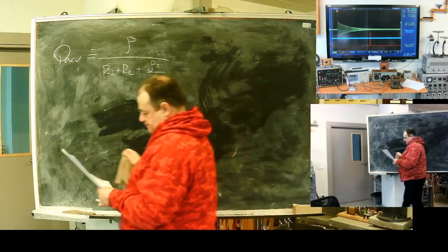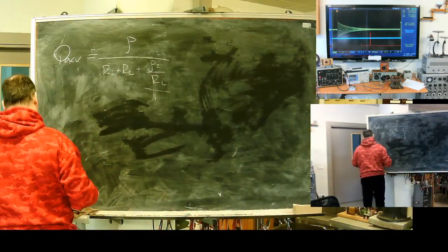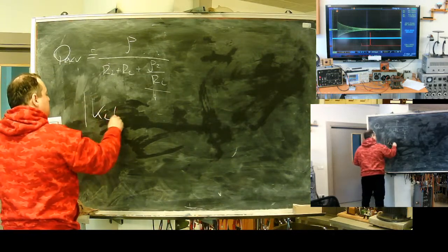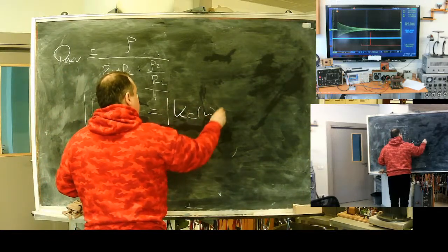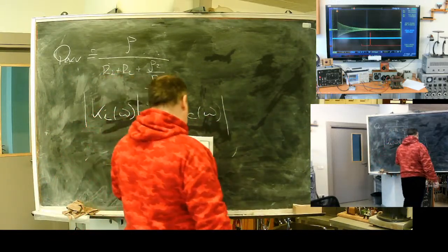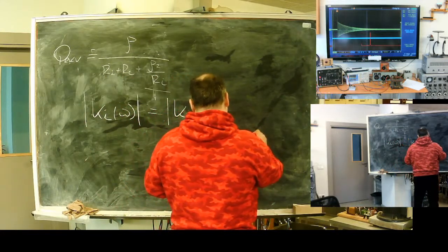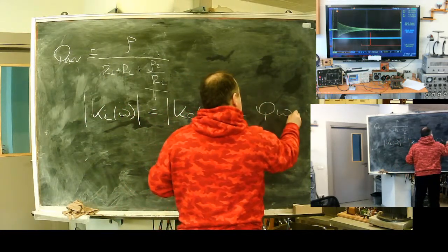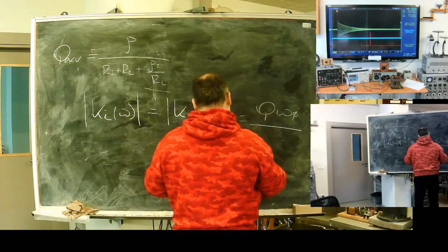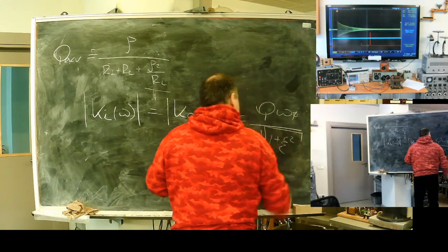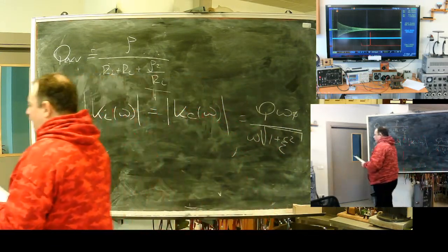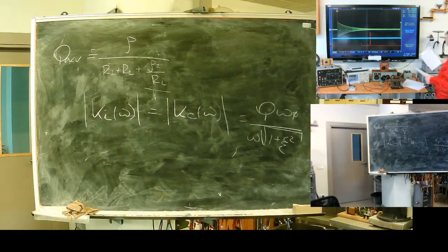In general, the transfer characteristic equals, when we take voltage from the coil or capacitor, not important, Q omega 0 divided by omega, divided by square root of 1 plus the frequency shift squared. What should I do? I need to show it. How can we make this visible?